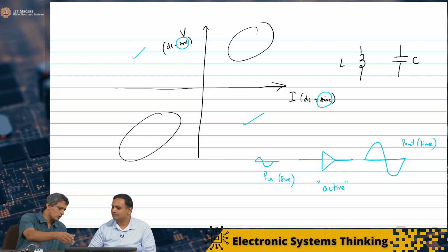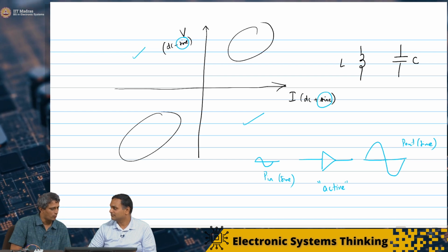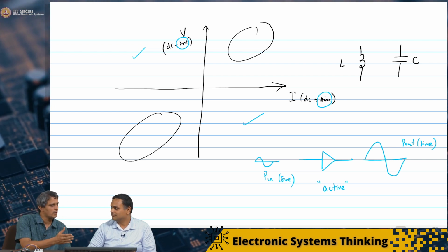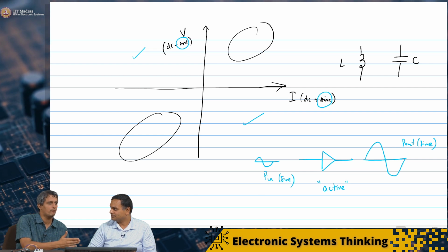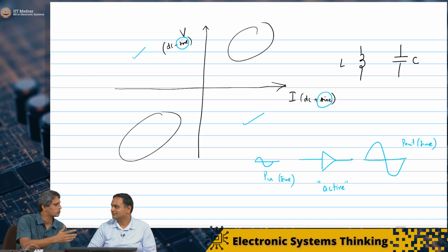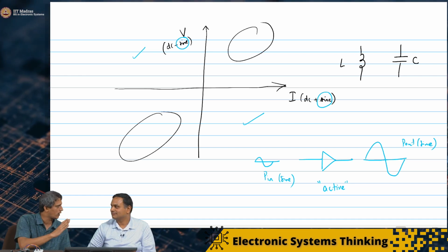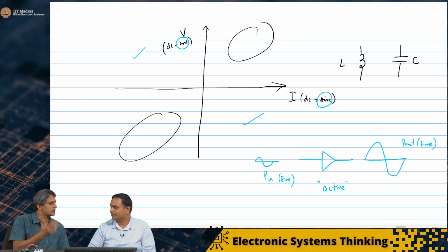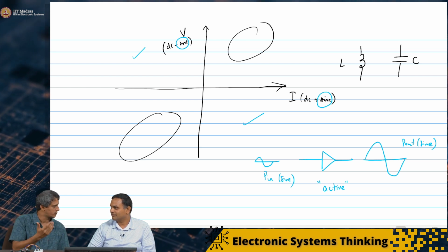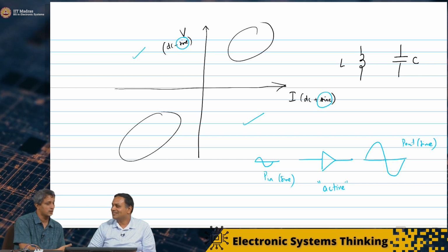I think this also ties in very well with the discussion I was having with Bobby, because the amplifier seemed to suggest that it could amplify any sinusoid, right? A sine omega naught t. Omega naught was not even in the picture. The amplification factor was independent of omega naught. So the natural question is, does this work for any frequency? 1 gigahertz, 10 gigahertz, 1 kilohertz, 100 hertz?